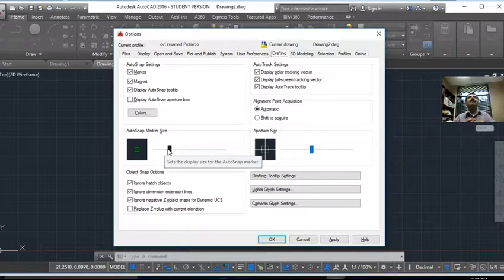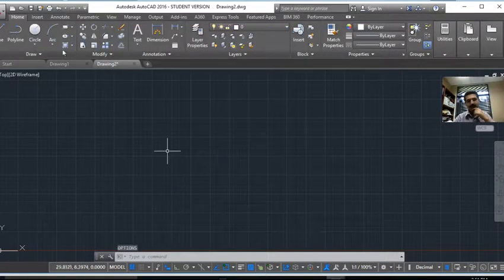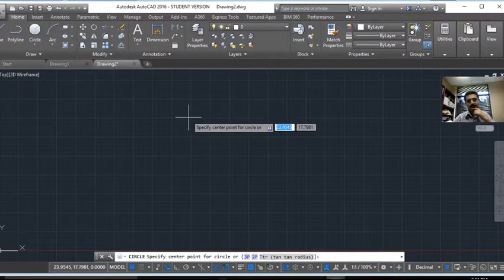It's basically if you have drawn a circle and now you want to draw a line from the center. AutoCAD has a great tool called AutoSnap or Object Snap that shows the important points along every object that you may think is an important point to start another drawing from. For example, a circle has a center and has quadrants, 4 different points of quadrants. How can I do this? Again, if you click OK, click a circle,